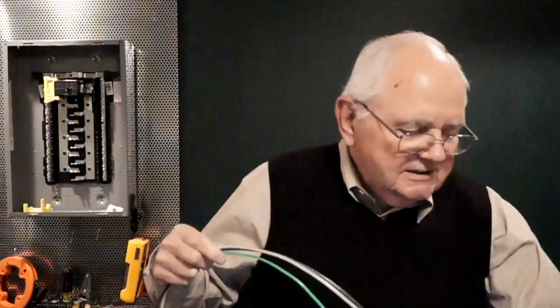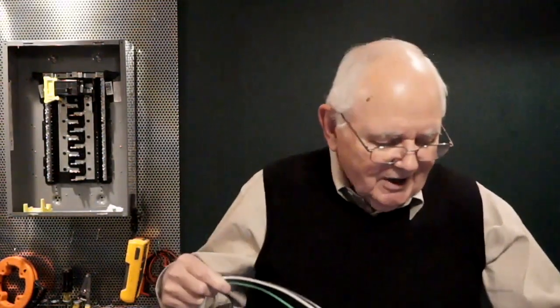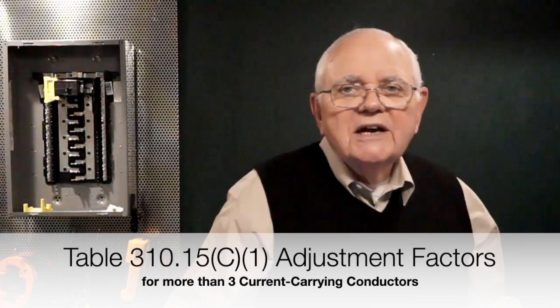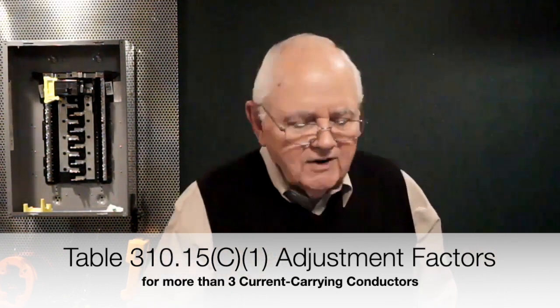But if I were to put more and more conductors inside of, well, maybe not this conduit, but something larger like the fiberglass or maybe some liquid type that I have, as I put more and more conductors in there, it just makes sense that it's going to be harder for the heat to escape from around those conductors. It's going to be warmer inside of a raceway when those conductors are carrying current flow. So I need to adjust for the number of conductors in my raceway. Well, table 310.15(C)(1) has my adjustment factors for the number of conductors in a raceway.